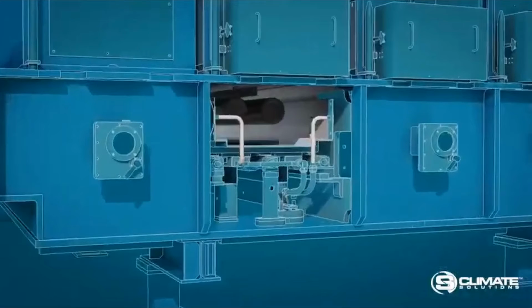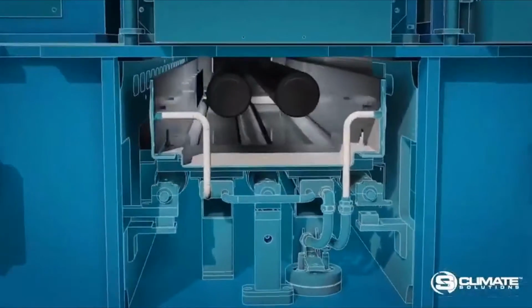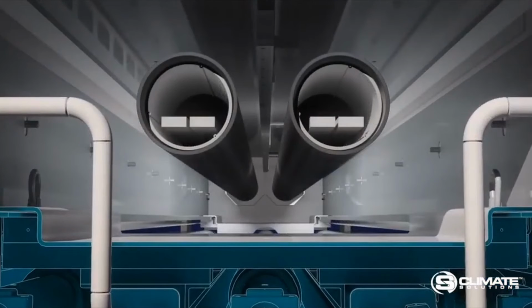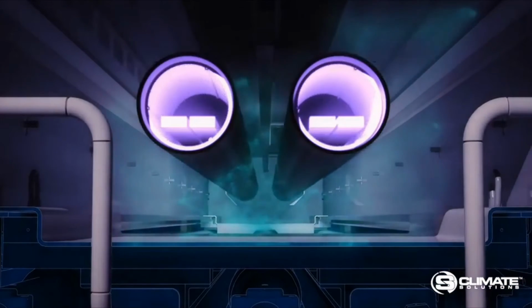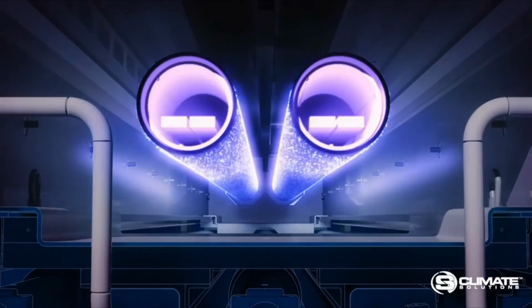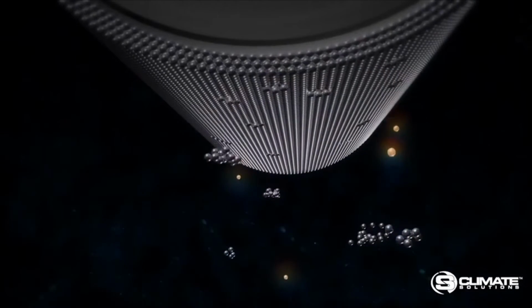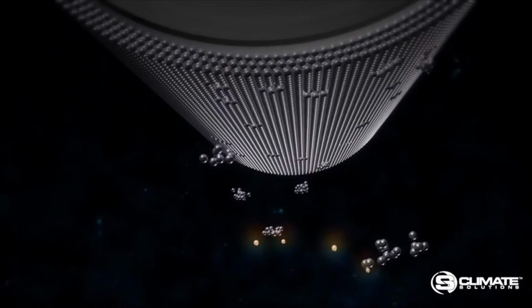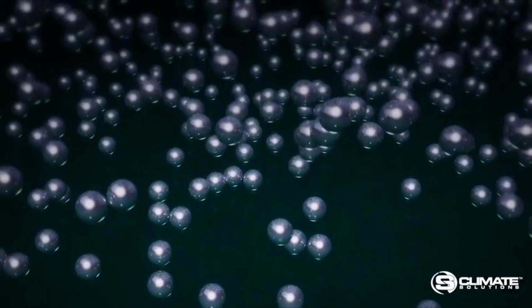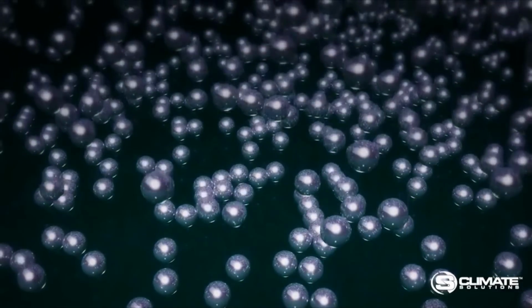DDP glass is classified as low-e glass and laminated glass, respectively as planar and curved glass. First, let's look at the process of making low-e glass. In the process of making low-e glass, magnetron sputtering technology is used. Each cathode chamber has a high-voltage magnetron. When activated, gas enters the chamber, forming a plasma. The positively charged ions from the plasma are attracted to the target material. These atoms are applied evenly to the glass surface, producing a thin film.